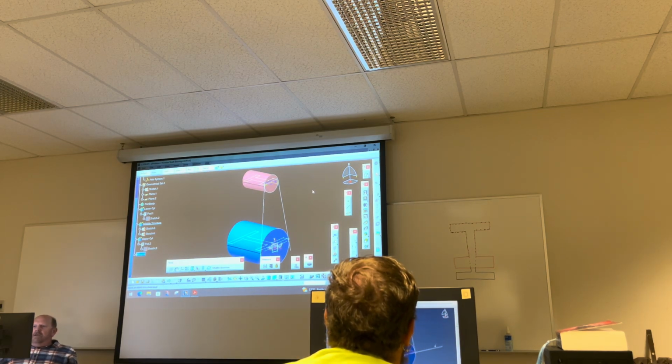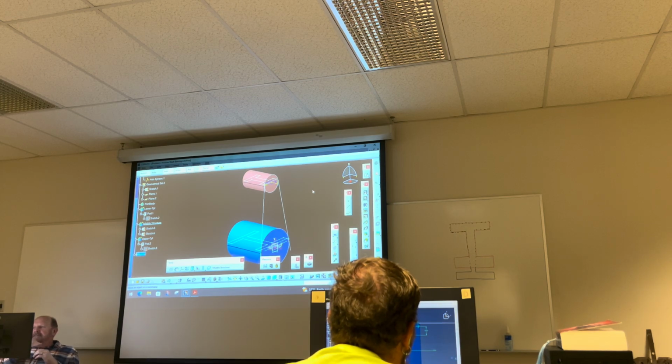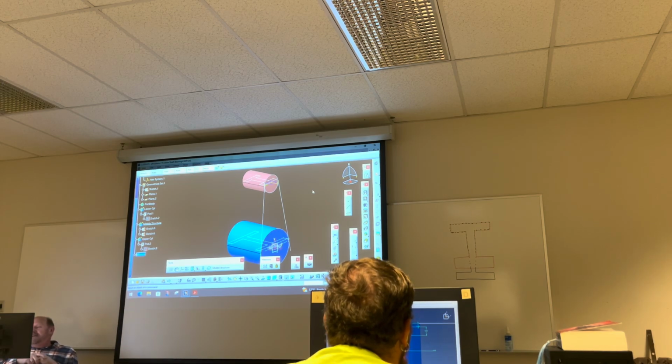Now, remember I created the lower cylinder, the middle structure, and the upper cylinder. And I'm not gonna do anything with any of the booleans right now, all right? And this is another one of those parts where I see a few students still just putting one body in, and they put all these features below it. This one, if you go back to build it and you don't basically put some of these in bodies, sometimes it'll get rid of half the solid. So that's another reason. So I'm just doing construction and I've got these bodies built. I'm gonna go back in now and I'm gonna do this multi-section solid.